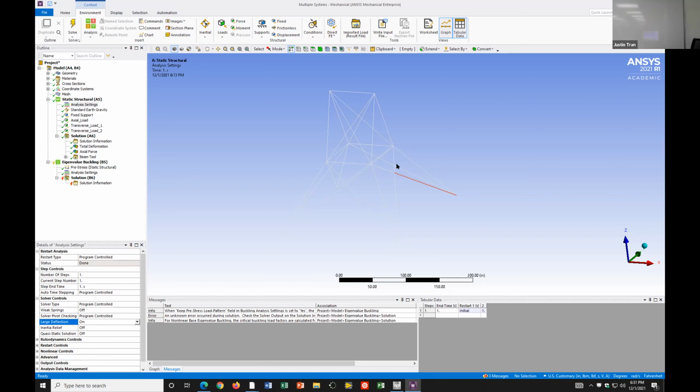If you do get a situation where you apply a load, because right now we're applying the loads gradually, but sometimes you can have a load that just gets dropped onto your structure. And if you have a load that exceeds the first one by this much, then this is what the buckling will look like. If you look at some of the higher modes, you'll see failure in multiple members. For the lower ones, usually it's just one member.